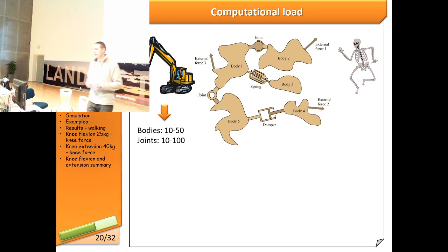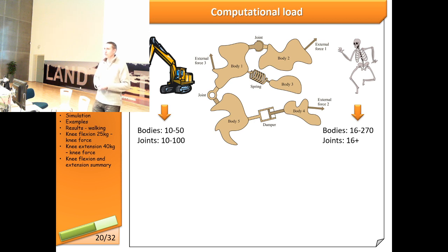And you can quite easily cut your structure and just take a fraction of it and simulate. In a human, cutting part of the structure to simulate is often done, but in many cases you would need the whole structure. And what changes here is that you might have many more bodies, and many more joints, plus much more complex models for the muscles, and they actually slow down the simulation a lot. And the contact models, which are almost always a necessity, you rarely can skip them.